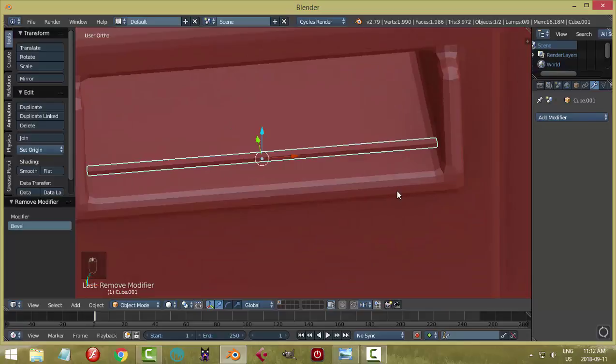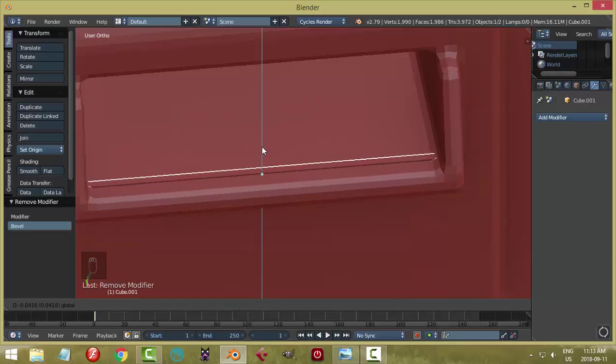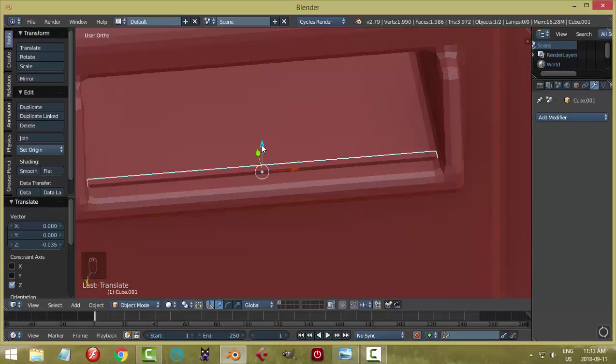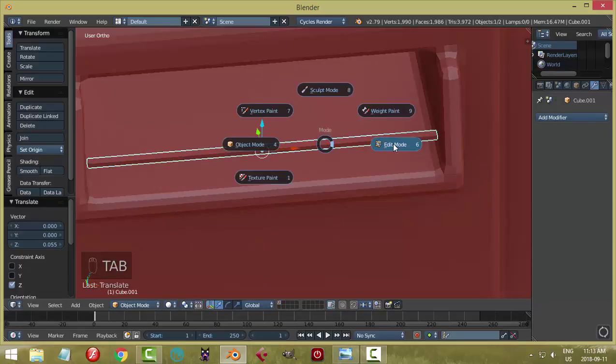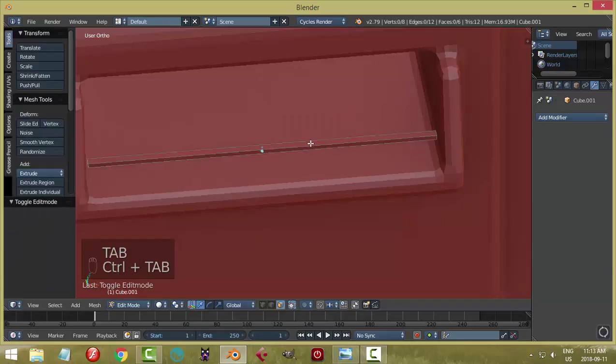Now it's flat. Now, because I want to somewhat reduce the polys, I want to delete the faces, if I can, that aren't going to be seen. The bottom of this, if I push this down, I'm going to make the treads out of this, isn't going to be seen, but I don't want to lift this up and try to find the bottom. I'm going to get rid of this top face, and then I'm going to flip it over. It's just easier to do it.